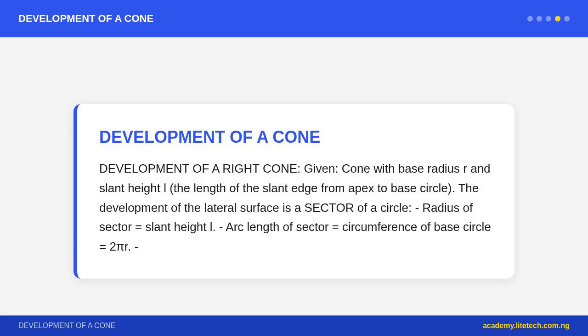Question 3. A cylinder has diameter 60 mm and height 90 mm. What are the dimensions of the rectangle in its development? Answer. Width of rectangle equals circumference of circular base equals pi times d equals pi times 60 equals 60 pi, which is approximately 188.5 mm. Height equals 90 mm, same as the cylinder height. The development rectangle is approximately 188.5 mm times 90 mm.